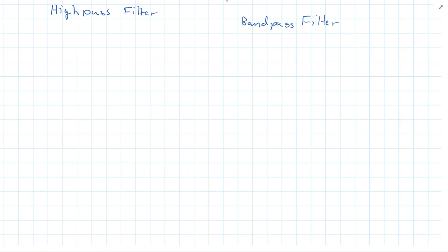Roughly speaking, and this isn't precise, you're letting in frequencies from 96.2 megahertz up to 96.4 megahertz, because that's what contains all the information for the audio signal. That's just a rough approximation, but obviously there's a bandpass filter because we're letting in a particular band of frequencies.